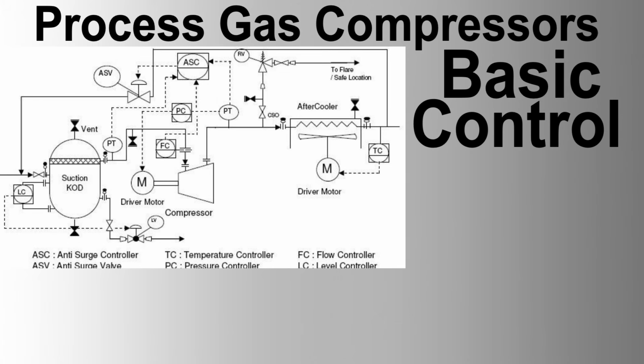B. Coordinated anti-surge protection. Anti-surge controllers must communicate to prevent cascading surges. Implement interlock systems to ensure that if one compressor approaches surge, other compressors adjust their operations to compensate. Configure the anti-surge control to activate recycle valves selectively based on the operational status of all compressors.